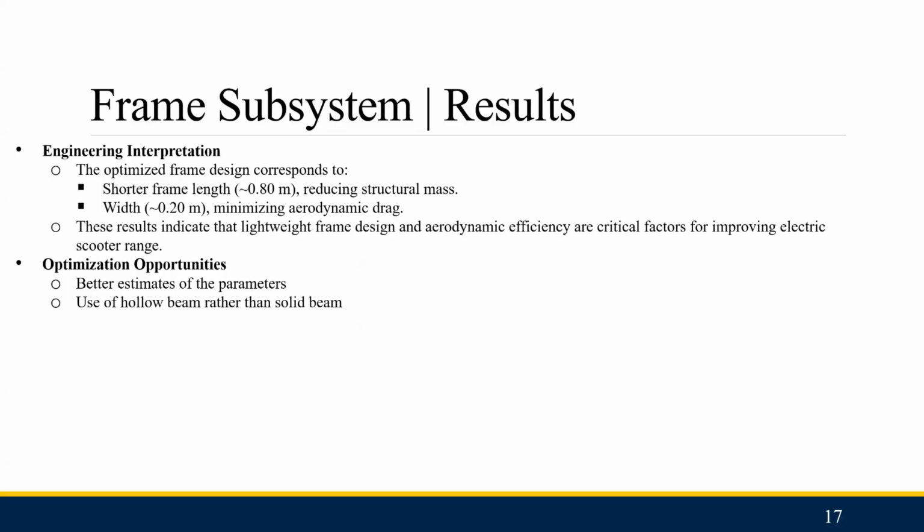As for our results, the optimized frame design corresponds to a shorter frame length, reducing the structural mass, and a width of 0.2 meters, minimizing aerodynamic drag. These results indicate that lightweight frame design and aerodynamic efficiency are critical factors for improving electric scooter range.